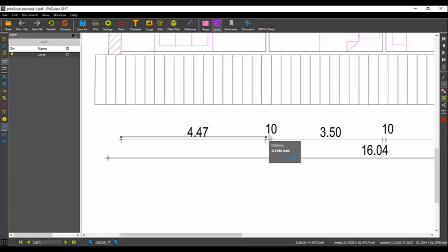Now, this is another secret about PDF. PDF files are not CAD files. This is only an electronic print, and the coordinates of this electronic print are in paper coordinates, like the print coordinates. Somebody printed this drawing on a small piece of paper, and PDF so decided, okay, good, now this distance is 34486 inch. And now if you measure, for example, this distance, I will measure from here to here. This is 2.7001 inch. And it's very interesting.